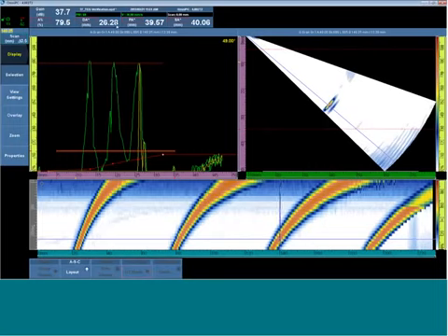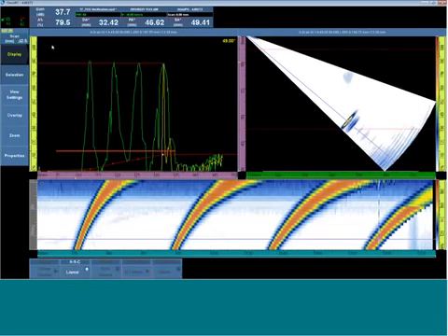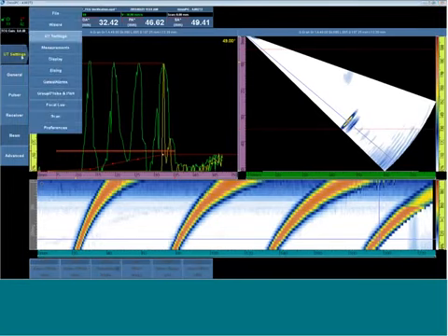Every A scan was calibrated for sensitivity and has a gain offset associated with it under the UT beam. Additionally, every TCG point for every A scan also has an associated gain offset. Through the wizard process, the software builds this.